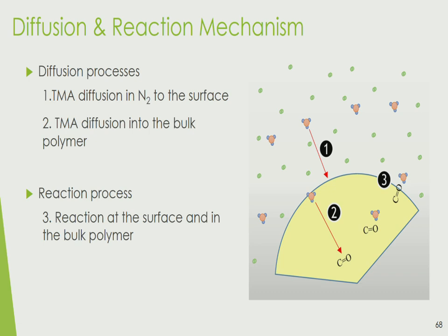If you have a polymer that's very reactive, like nylon 6, it will stay at the surface and prevent further diffusion in later exposures of your precursor. If you have a less reactive polymer, or one with more free volume based on its structure, then you can get more diffusion in, and it will react within the bulk of the material.